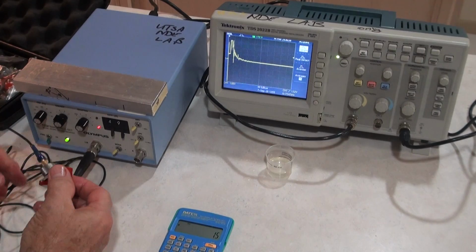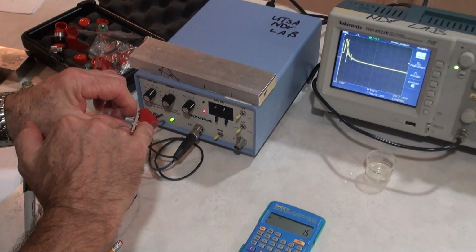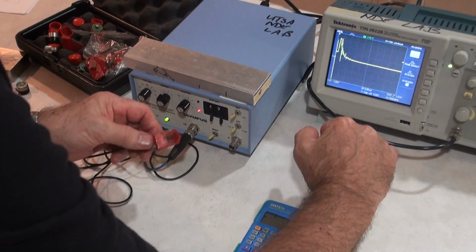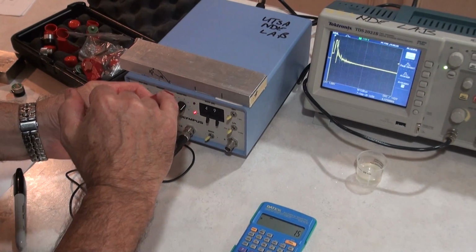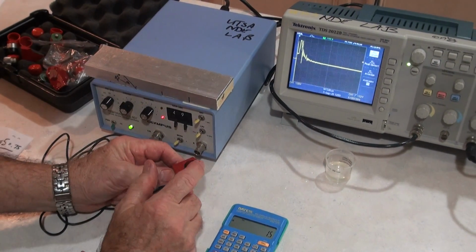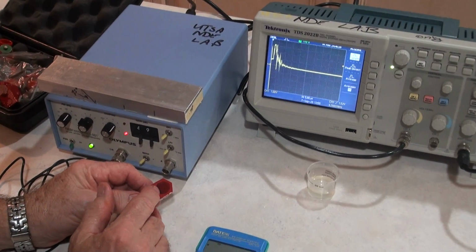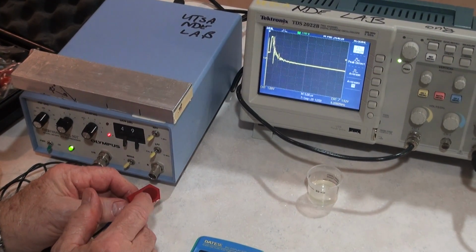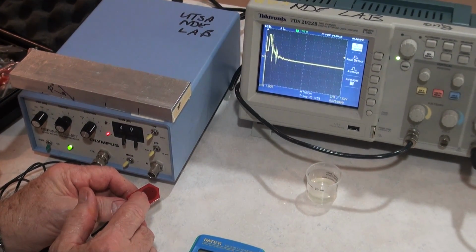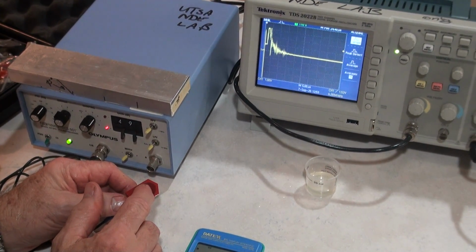Okay, and part of the signal is traveling in the wedge, so we need to know what that is. So I want to test that again by looking at the oscilloscope. And what I notice is that as I couple my finger into the oscilloscope, I get a signal here that is fairly large. See it right there?